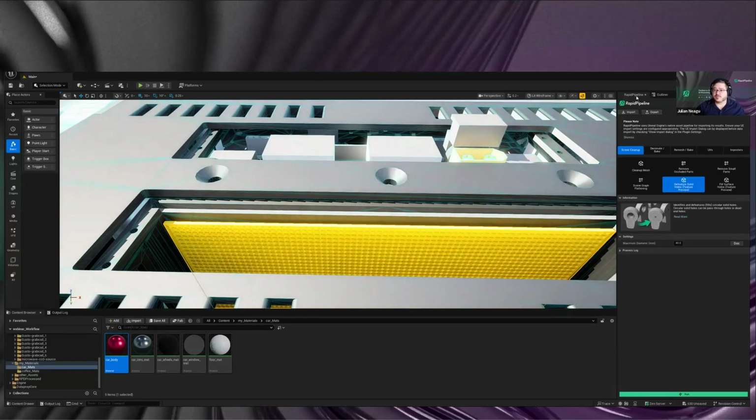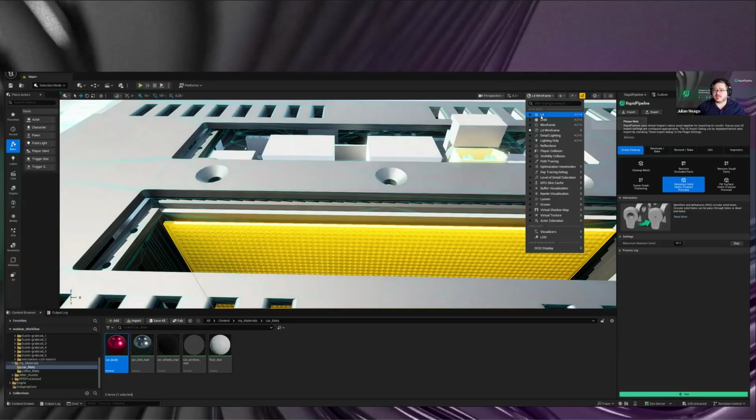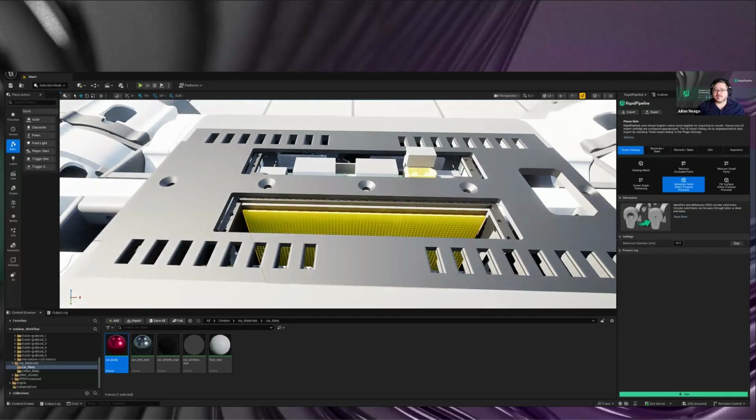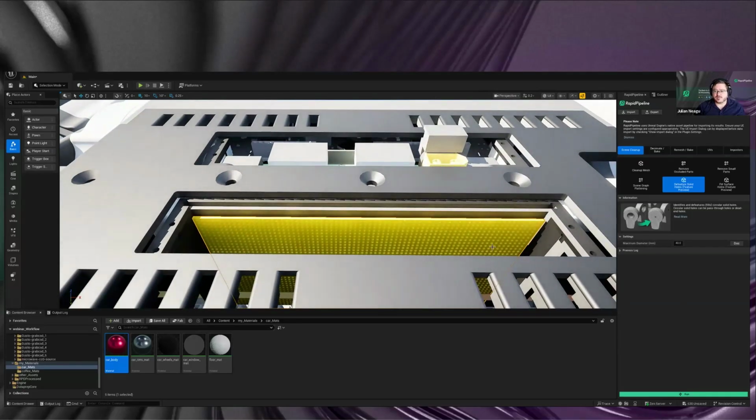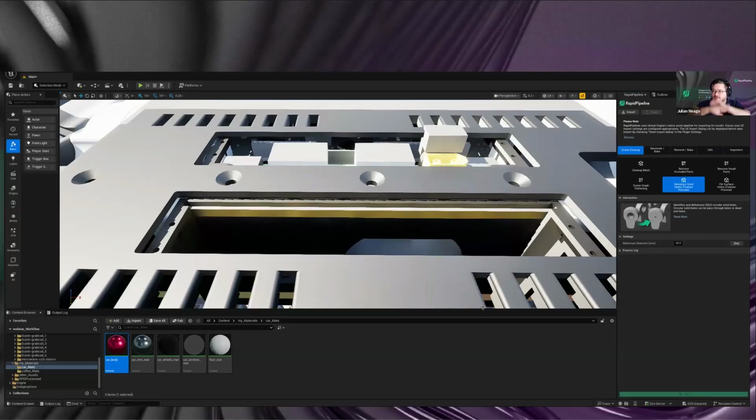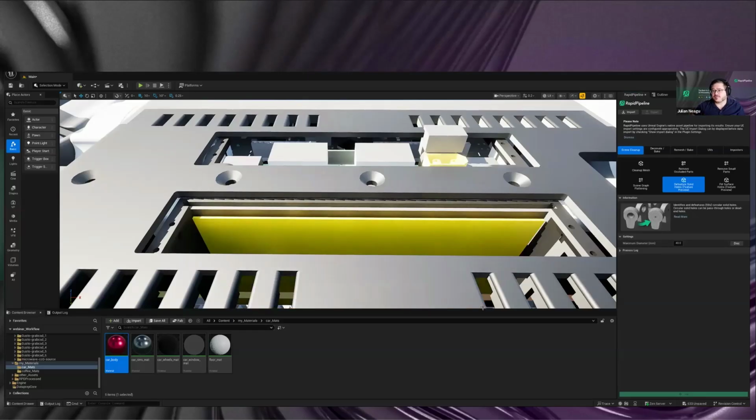Let me go back to the lip mode, and let's selectively run this on these types of holes. Right now, the default is 40 millimeters, so 4 centimeters in diameter. That's basically the maximum threshold, so it wouldn't close any holes larger than that, but you can always adjust it. You can run it on a particular part like I'm doing right now, or run it on the whole model and see what happens in terms of the size of holes which are closed.